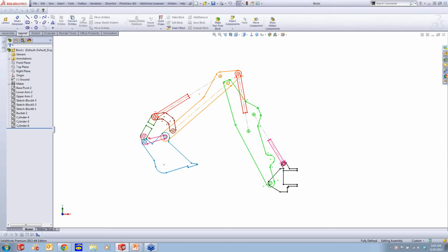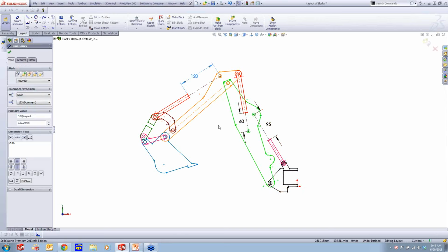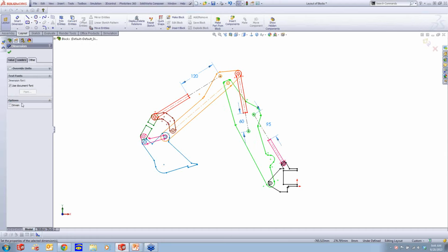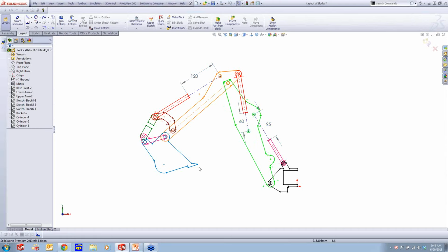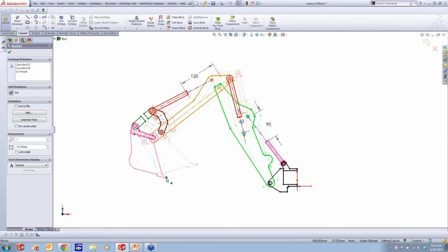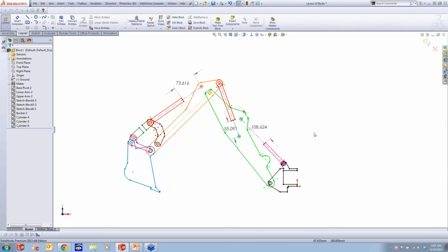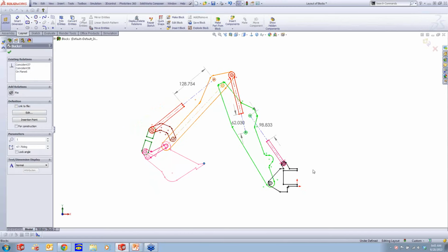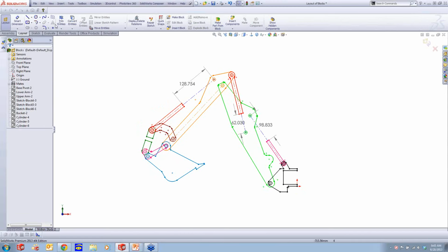So essentially the way this works is there's a tab here for layout, so you can edit the layout of the assembly. Here you can see I've got a number of different blocks, and then I have a couple of dimensions that are restraining the lengths of these cylinders. If I turn those off, I'll just turn these to driven here for a second, so that I'll be able to move these components around. You can see as I drag the sketch, all of those blocks are going to react to their individual constraints, to those sketch restraints. So you can see I've got a number of constraints that are holding things in place there.